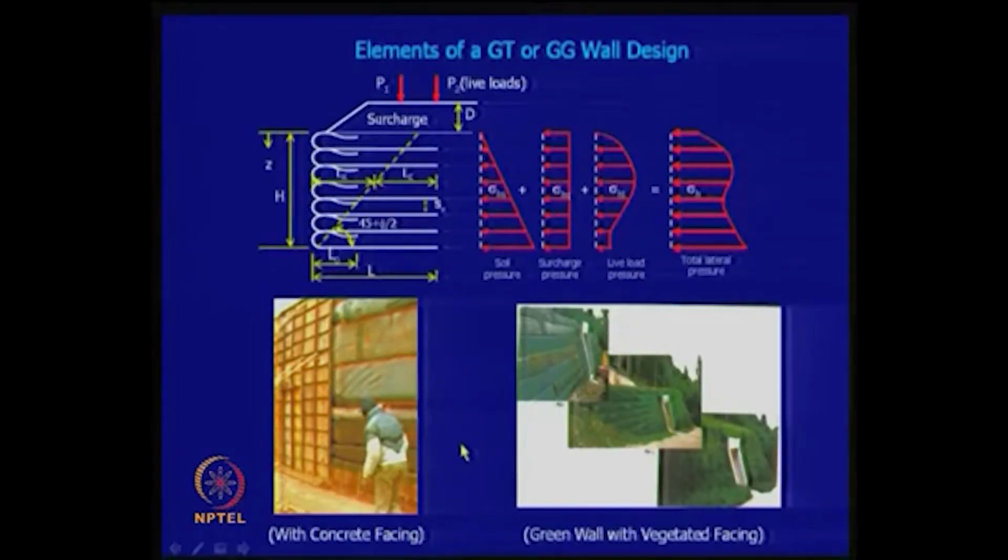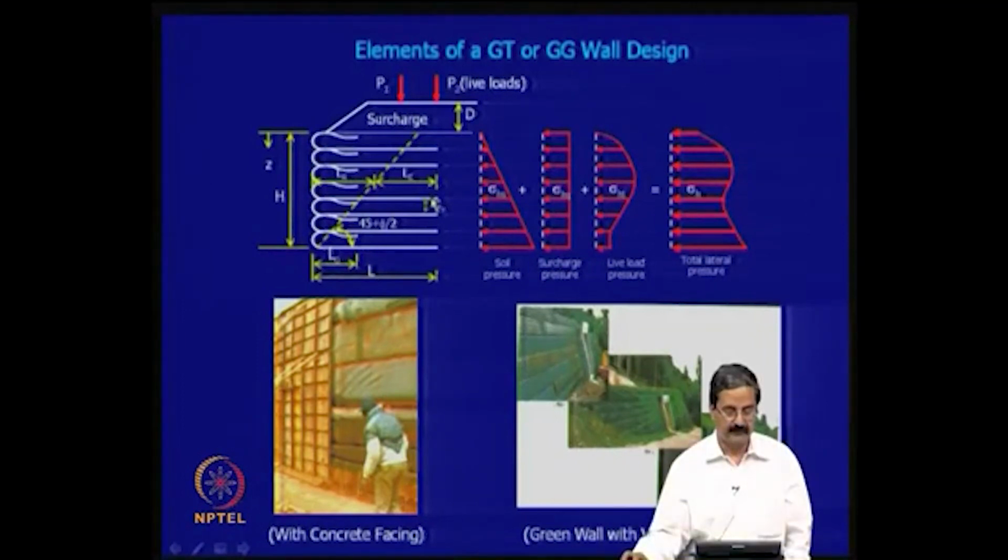This is a simple example, like as I just mentioned, this is a geotextile, actually we call it a wrap around geotextile, okay. And we have studied that the failure wedges can form in different angles. So, this is 45 minus phi by 2, this is 45 plus phi by 2, this is a retaining wall, and you have geotextiles placed like this, the way we will see how it is done also. So, you have a surcharge P1, say you try to construct some road there, that is called surcharge.